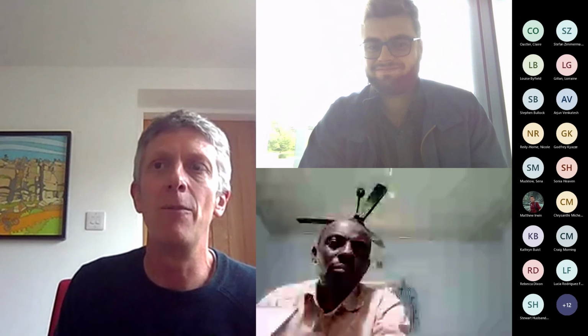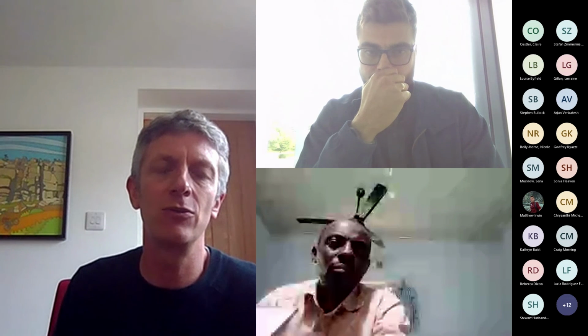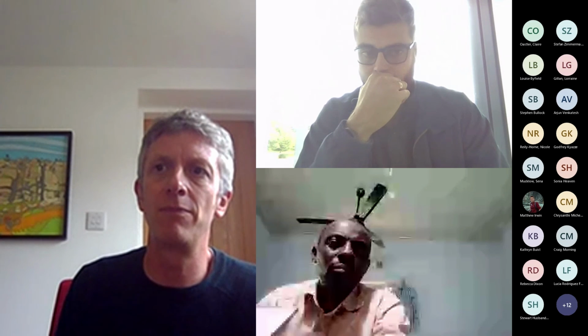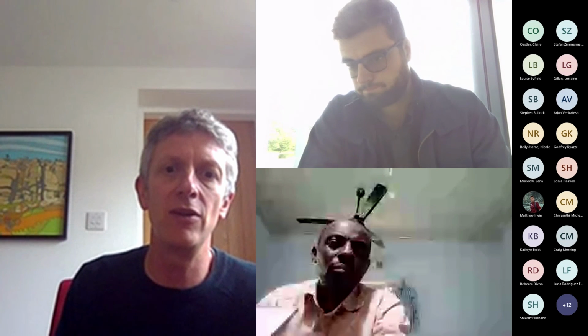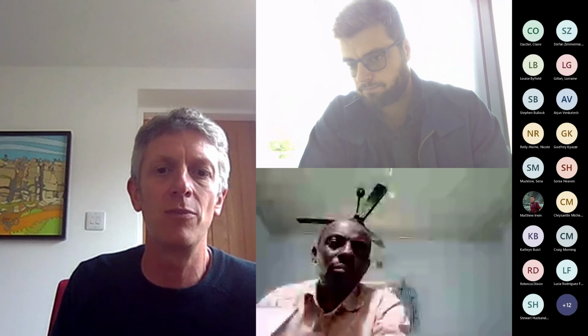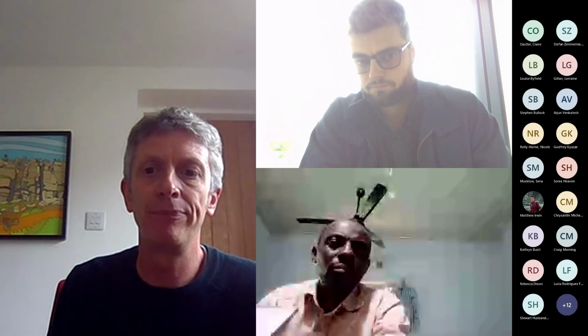Basic question, well, what the hell is the other 60%? Where does that come from? Which I think probably is the biofilms in the pipe and the legacy, but definitely coupling more, making sure we don't try and draw this hard boundary between treatment processes and distribution systems is really important. There's lots more we need to discuss there, both in terms of what the treatment works lets pass through in terms of the community, and it can't remove all of them, but also in terms of the different nutrients we're putting into the water or passing through, and the background levels of iron, if that's a coagulant, or from the source water, levels of manganese coming through.